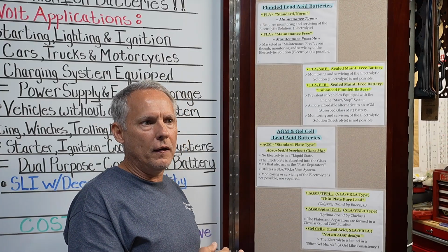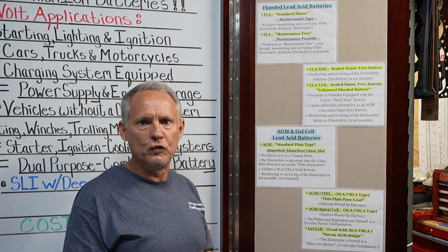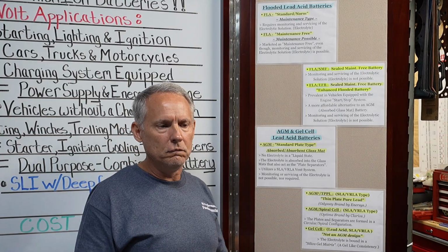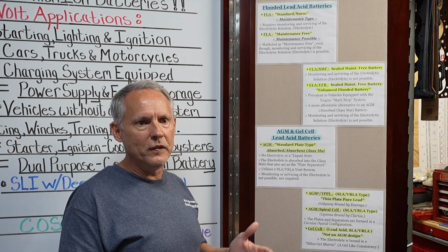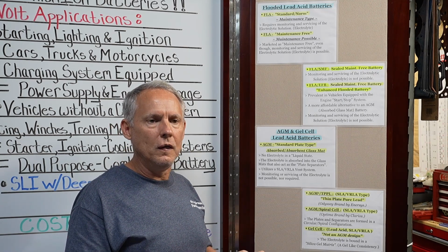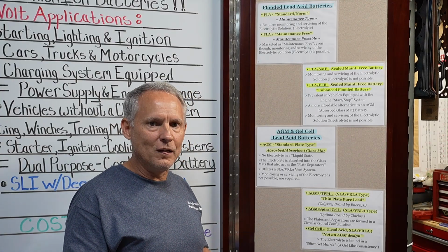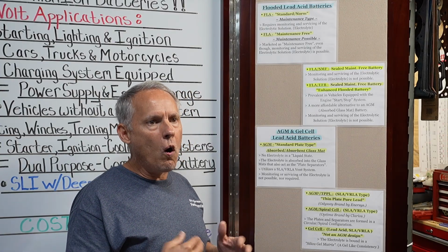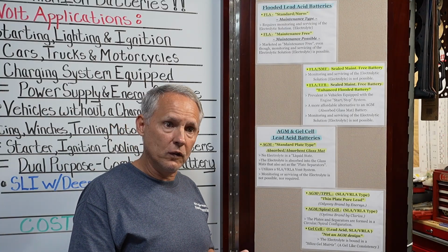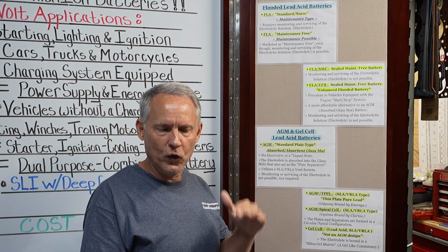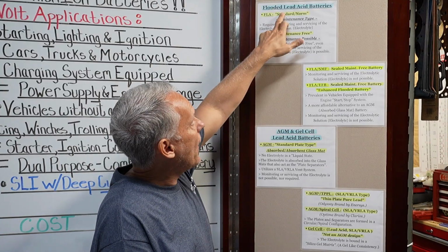I think a lot of people would tell you that flooded lead acid is all there is, just flooded lead acid and lithium ion, one or the other. I don't necessarily agree with that. The flooded lead acid batteries, to me, have a liquid electrolytic solution or a liquid electrolyte, and lead acid batteries don't all have liquid electrolyte. So I'm going to break it down for you a little bit, kind of separate it. So to start with, the flooded lead acid battery.